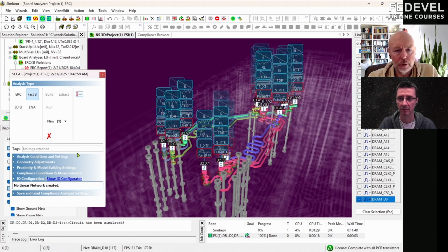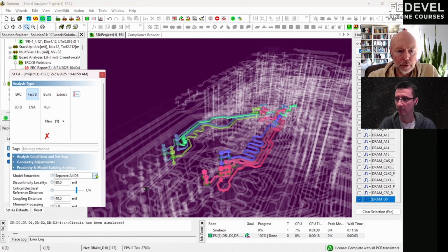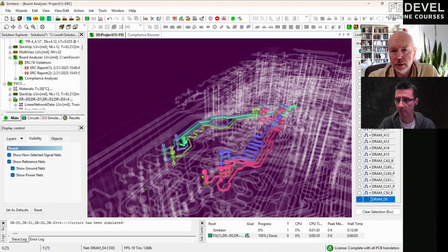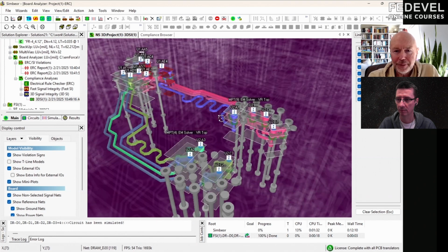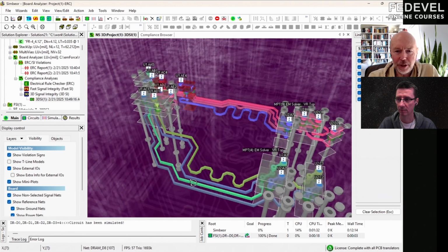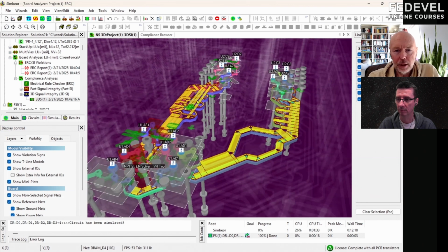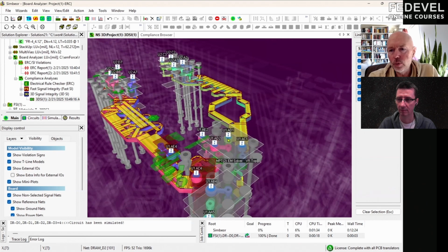not just those links, but links in general, in high speed links, for instance, and take into account, for instance, coupling between vias, just a few clicks, build a new 3D analysis, automatic. And again, now it builds, it splits the whole structure into transmission line sections with coupling, obviously, and accounts with 3D electromagnetic analysis for coupling between those closed vias.